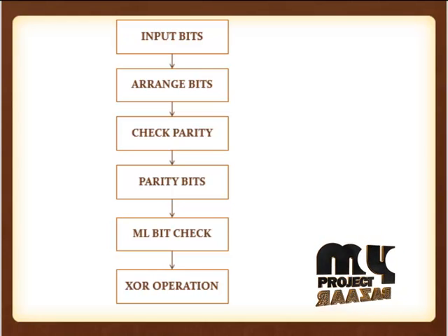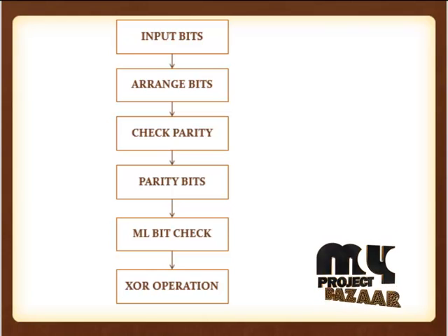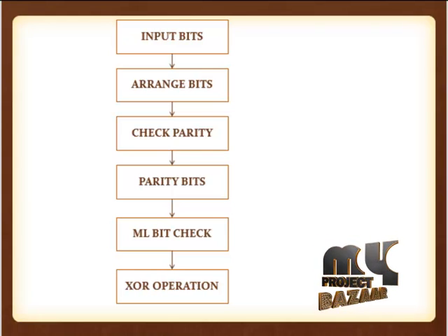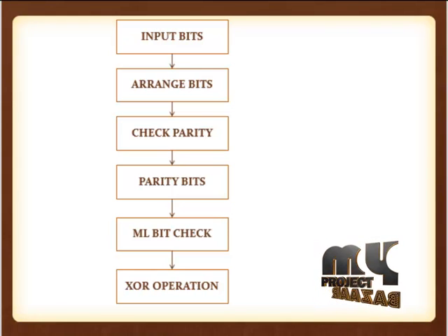In this process, we first find the maximum likelihood bit range of the neighboring bits, then decode using the MLD algorithm. The MLD algorithm does the bit check process. We correct the error bit by checking the lost bit from the shift register and the bit from the majority logic circuits. In this error correction stage, we use an XOR gate that changes error bits if there was a change in bit. We compare the lost bit from the shift register and the bit from the majority logic circuit, and finally correct the error bit.